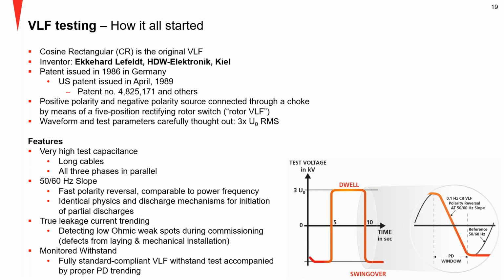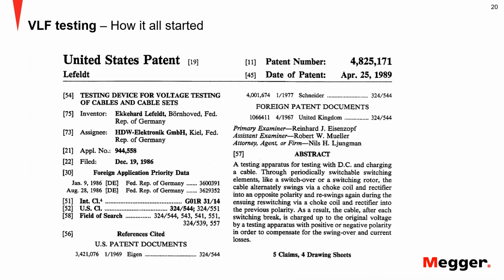The slope of the waveform makes it applicable to PD testing, as was confirmed later on in several practical studies in 2006, 2008. And you can do a very nice monitored withstand with this. That means you do a VLF withstand test and you trend the PD while you're doing this. Here's just the patent, for the interested, for the experts amongst the viewers.